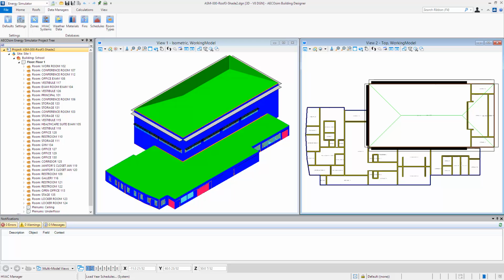Welcome to this session on making modifications to the HVAC system. In this session, I will guide you through making various updates that will impact the energy usage by modifying the heating, ventilation, and air conditioning system. Every HVAC system has different key variables that can be adjusted to alter the system's energy usage. Examples would include the coefficient of performance, supply air fan efficiency, motor efficiency.